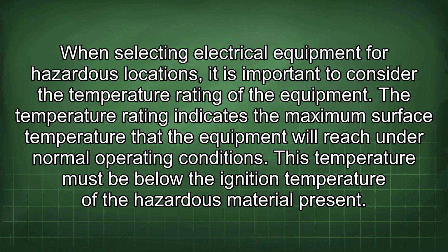When selecting electrical equipment for hazardous locations, it is important to consider the temperature rating of the equipment. The temperature rating indicates the maximum surface temperature that the equipment will reach under normal operating conditions. This temperature must be below the ignition temperature of the hazardous material present.